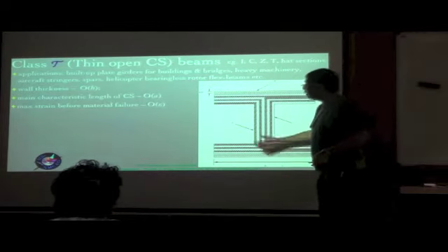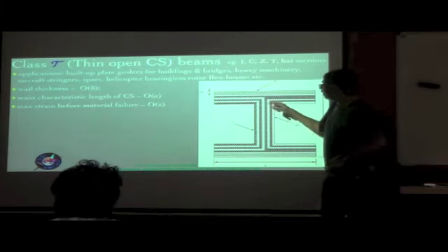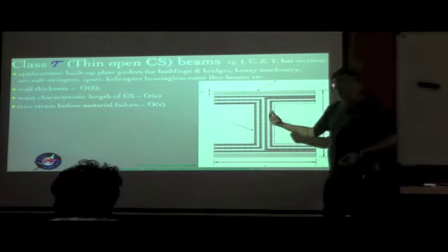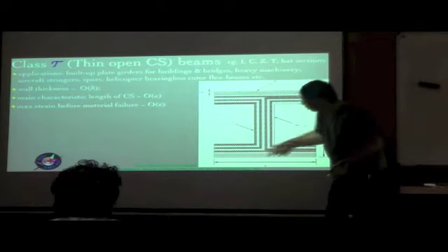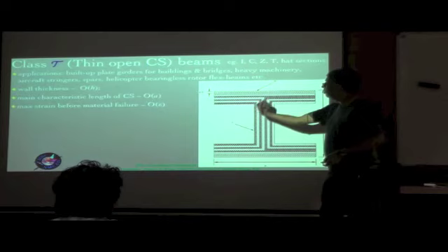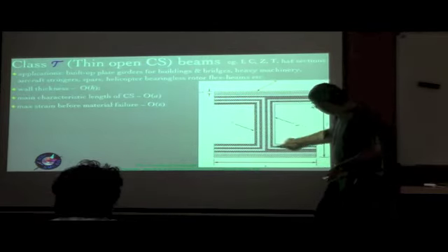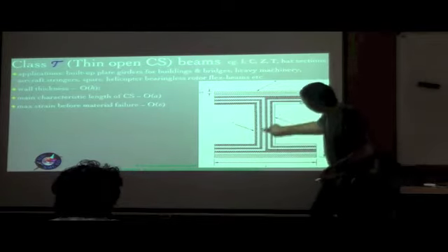So somewhere you cut along the beam on that cross section, that torque has to be resisted by means of a shear flow, and because it's not a closed cross section but an open cross section, there has to be a shear flow which is in the opposite direction. So there will be a shear flow which goes around like this and comes around like this.